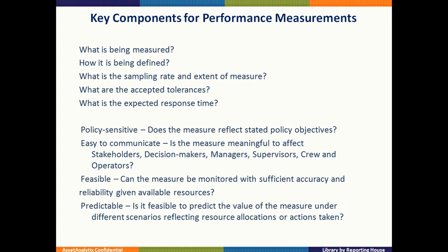Then in some cases, we got to determine whether that KPI is feasible to generate. Like in the case of MTBF, it could be very difficult if the correct data is not taken into account. Many times, a CMMS system may not actually record the time the asset went down.